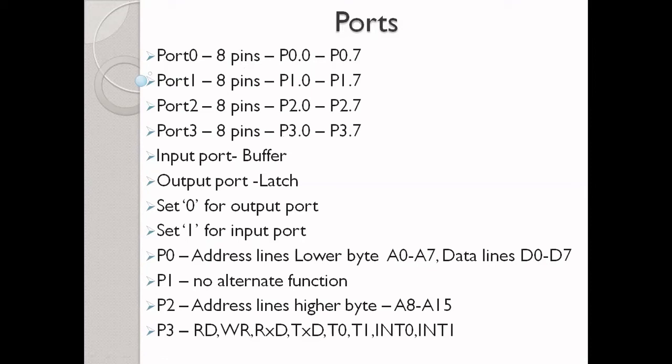In the ports, there is a buffer and a latch available. If you select the port as an input port, the buffer will work. And if you select it as an output port, the latch will work. So if you give the value 0, the port will be set as an output port. If you set 1, the port will act as an input port.